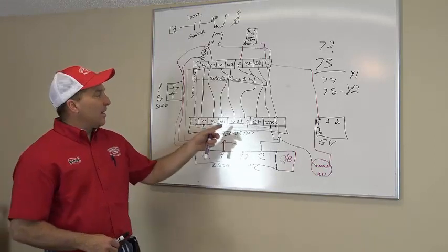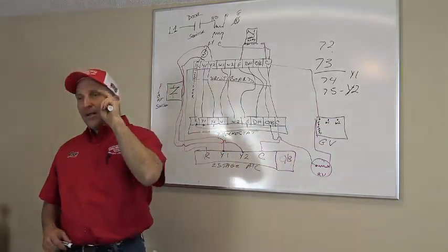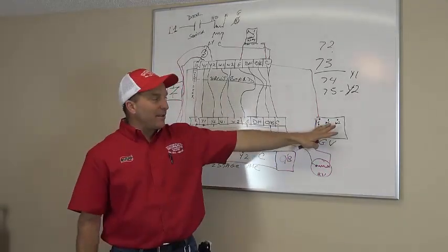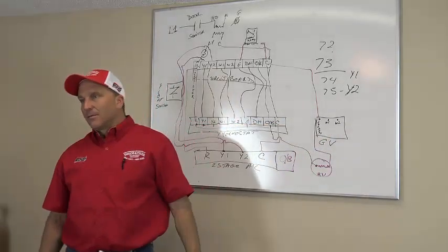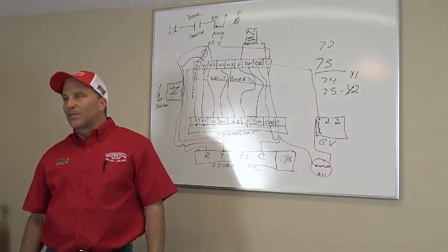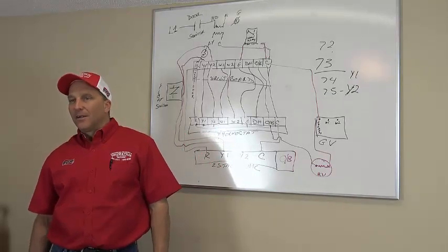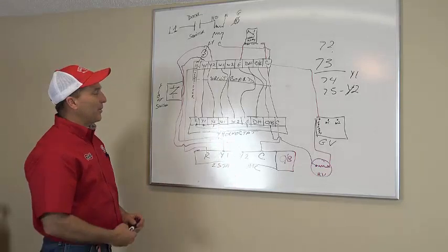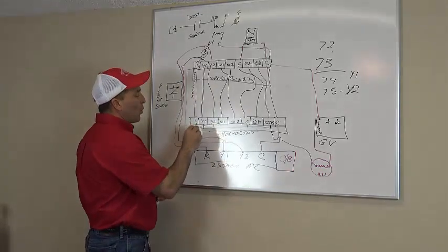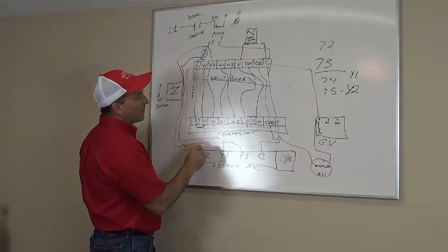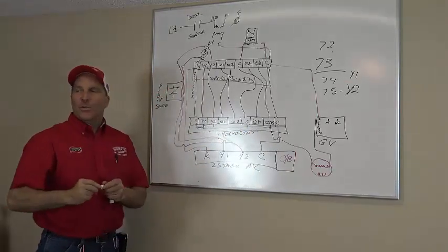If I energize W2, I got to energize W1 first, and then W2 energizes. Now I've got, again, a gas valve energizing, which is going to run my gas furnace. I'm not energizing my gas furnace. I'm energizing my heat pump. Listen to Gary. Gary knows what he's doing. Gary, what are we energizing? Y1. We're energizing Y1. So Y1, right? G and O. So what gets energized right here in my heat pump?